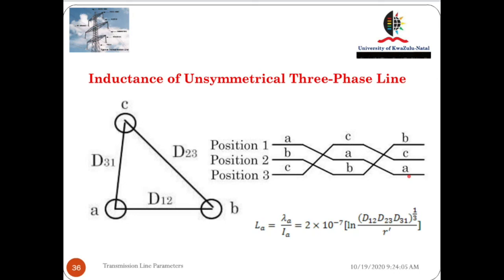And when we do this in real life, we don't take these distances between them to be very long. We want to finish this very quickly. Within a short distance, within hundreds of meters, we are done with transposition. Then we carry them all the way, because now they are balanced.